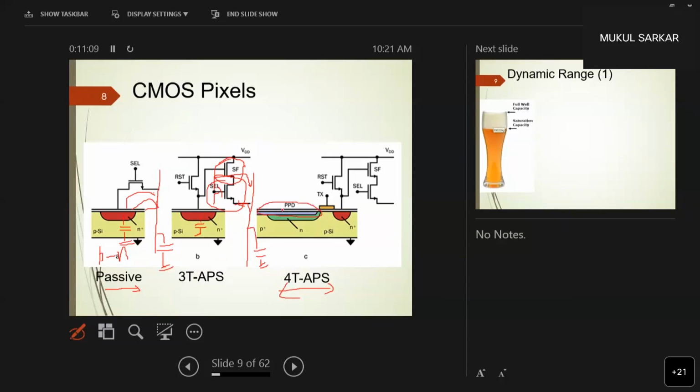So the substrate of a silicon is usually not very planar, and therefore it introduces a lot of noise. This PPD actually helps in reducing the interface traps available on the surface, and therefore reduces the noise. If you remember that this PPD structure helps to reduce the noise on the pixel side, that's good enough.